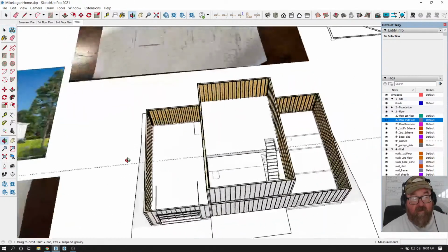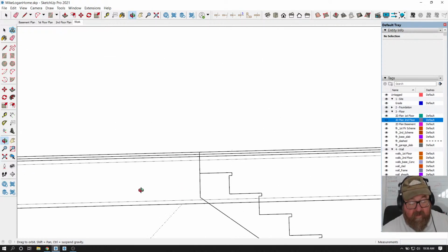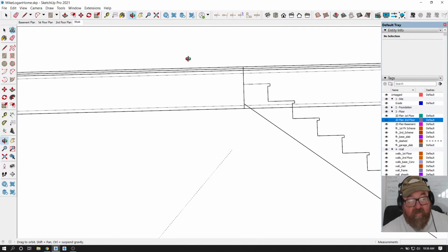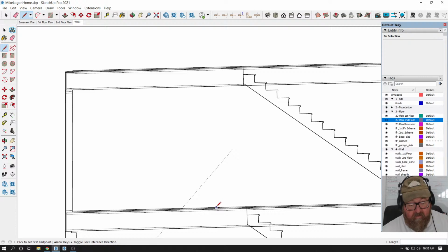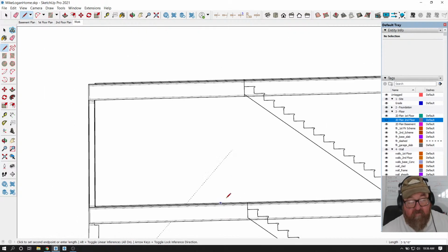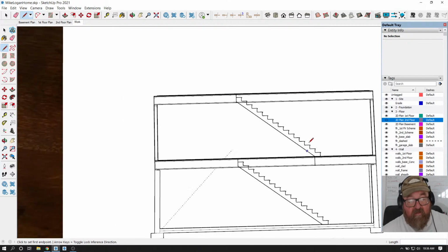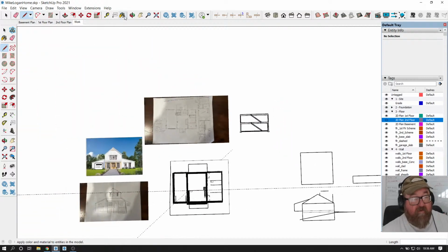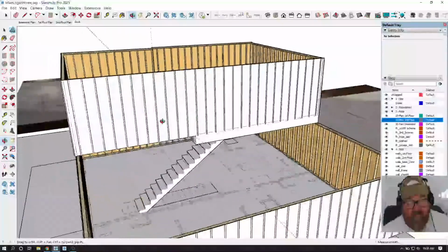You see, this is also why we do 2-dimensional sections of the building. We go in and we do our wood I-joist, we do our subfloor, we do our finished floor. Then up here, yeah, that's 16. So see, 2-dimensionally, I can measure, and I know that from my bottom floor to my top floor should be 10'5 7/8". And that's what this section is for, that kind of reference. So you see, we can't just ditch our 2-dimensional drawings forever.